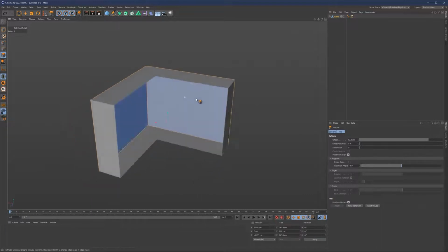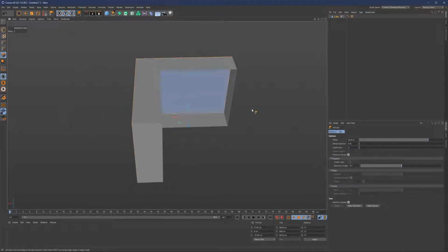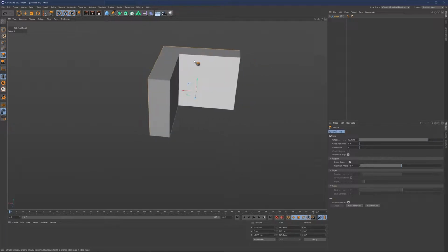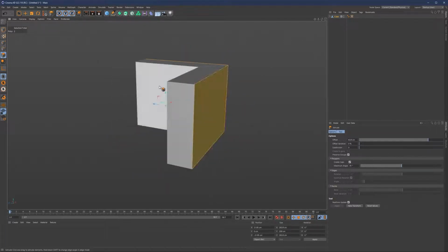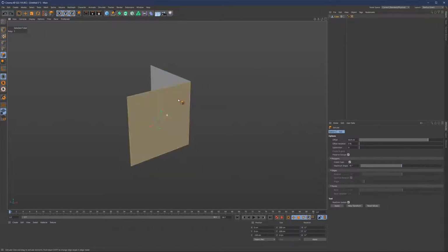And by default, you're probably going to have open edges here on the back. And if you don't want that, then you will simply use the create caps option. And basically that is what it does. It simply closes any open holes that you're going to have during the extrusion. All right, so let's go a couple of steps back.